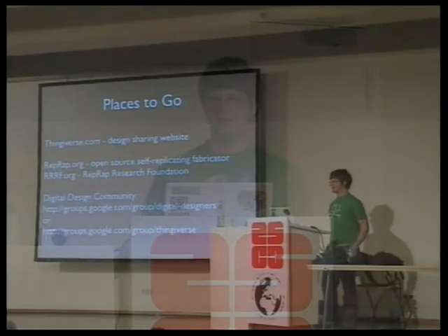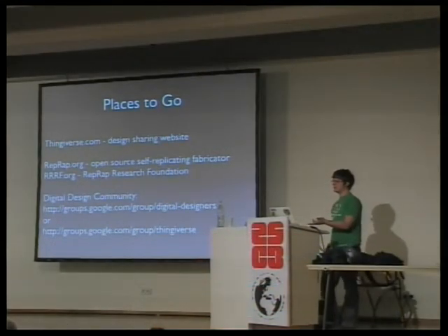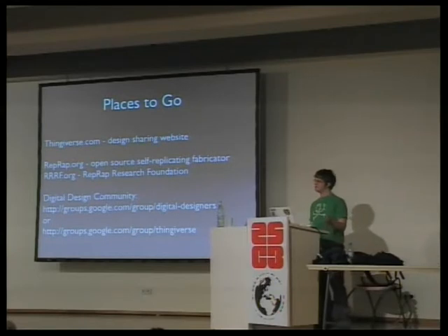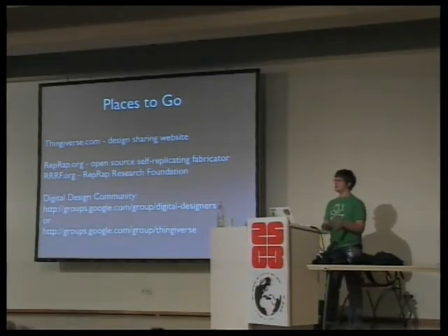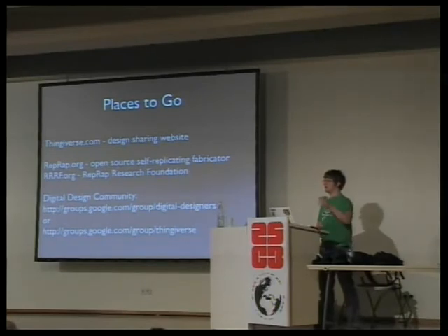For some sort of markup language, it really just needs to say, in coordinate system X, do Y. I'm a little surprised that doesn't exist. It does exist, but it's more machine specific. There's no overarching single language. There's something called G-code, which is what the vast majority of CNC machines use, but that's like go X to Y to Z. So the generator that produces that code needs to know information about your machine in particular, like how big the drill bit is on your machine and so on and so forth.